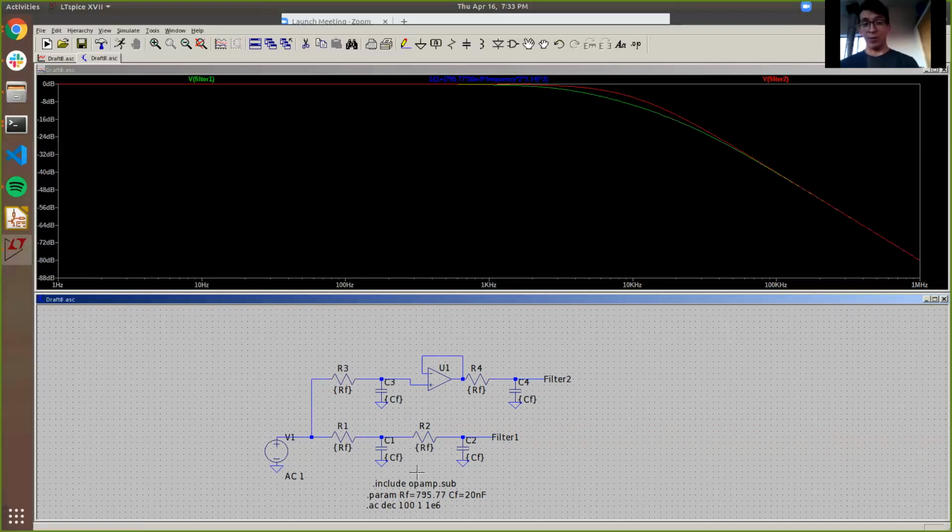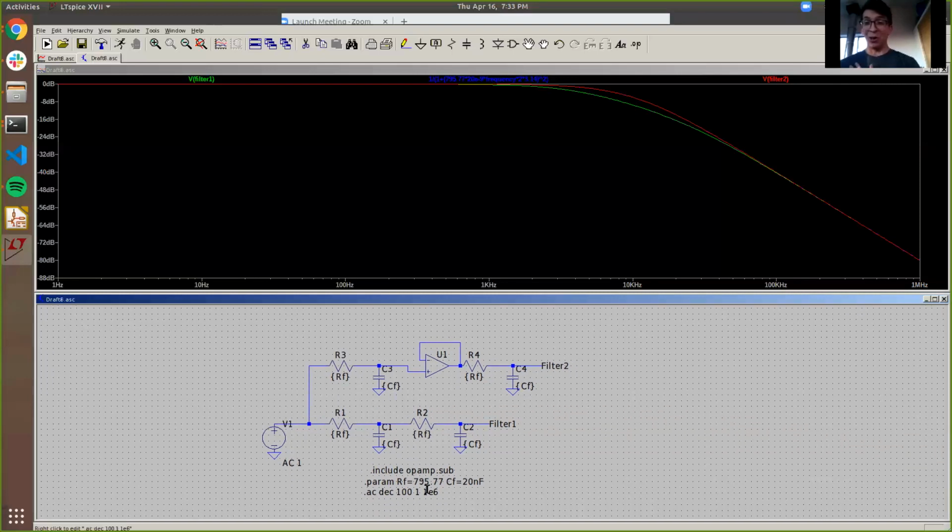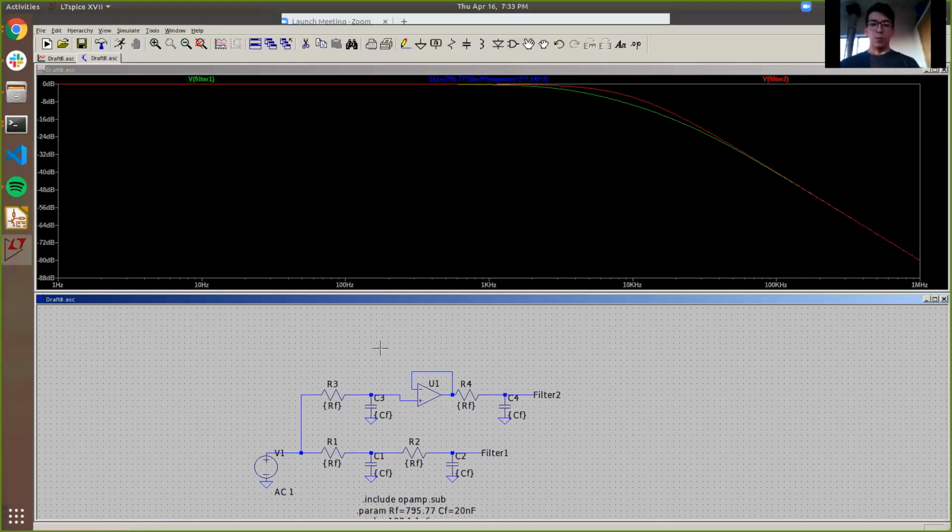In this case, the resistor value is almost 800 ohms. That's a lot of heat, assuming you put 5 amps through it, or if you had 5 amps on the other side. That is unnecessary loss that you could avoid by using a better filter. In this case, you could use an LC filter. So we're going to simulate a quick LC filter.